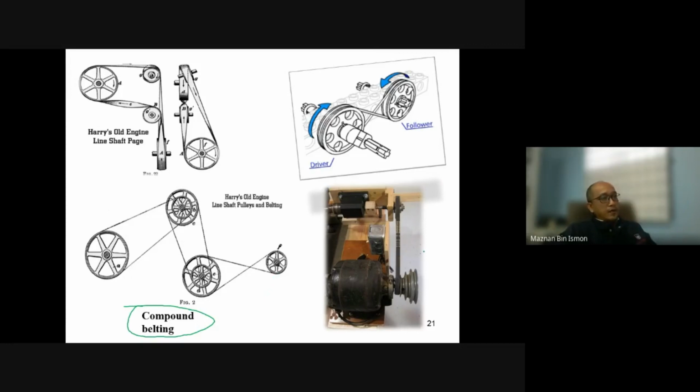If you refer to the bottom right, this is the pulley, with different sizing, different diameters. 1, 3, 2, 3, and 4. This is a 4 groove pulley. So it is simple. If it wants to change the speed, it will shift to the bigger one, and this one will be offset over here to make sure the belt is in good alignment. Otherwise the belt will twist.